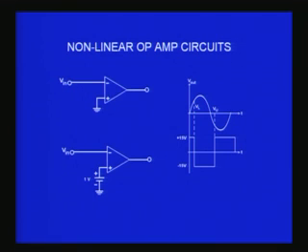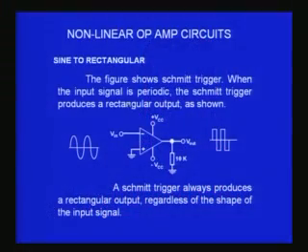So then the transition point can be shifted wherever you want. If it is 1 volt, when the other voltage exceeds the 1 volt by plus or minus 140 microvolts, then you will get an output which is a square wave. So you can see that you can also provide an additional bias or level to the comparison of the two voltages. That is exactly what I have shown in the next slide.